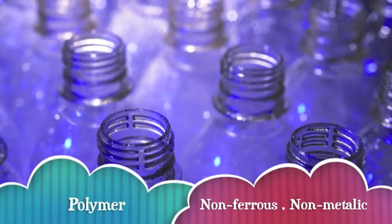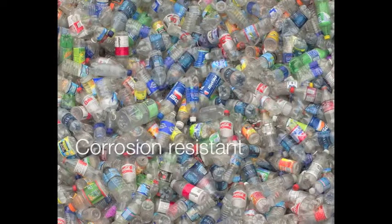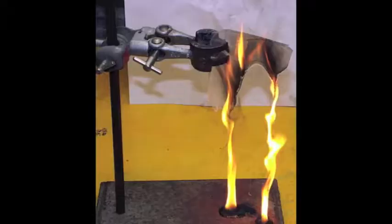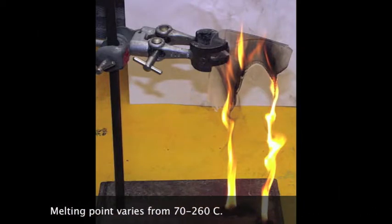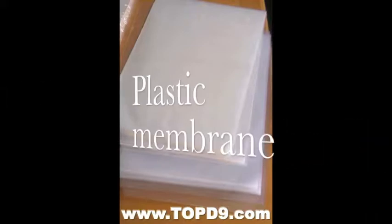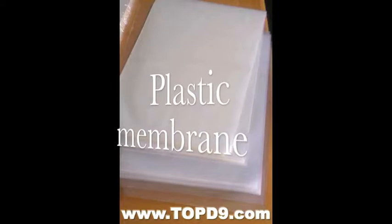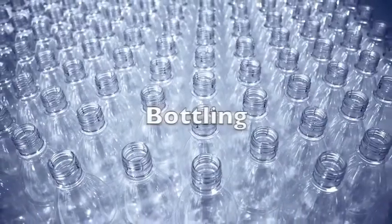It's a polymer, non-ferrous, non-metallic. Plastic is man-made, lightweight, waterproof, corrosion-resistant, easy to shape, and it's an insulator. Its melting point varies from 70 to 260 Celsius, depending on the type. Low thermal stability. These outstanding properties, especially the ease of shaping, allow plastic to be in a lot of diverse applications, such as plastic membrane for other materials, medical equipment, bottles, and mostly in packaging.